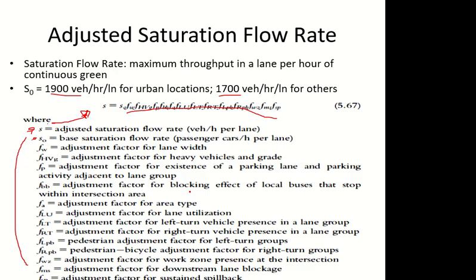So if you have a bus stop which is near the intersection, the bus is supposed to stop at the designated point, and this is stoppage. So when the bus is stopping, it will go in and come out of the bus stop. So this can block the movement. Signal could be red, could be green, but people may have to wait for the bus to go into the stop and come out of the stop. So this is the blocking effect of the bus.